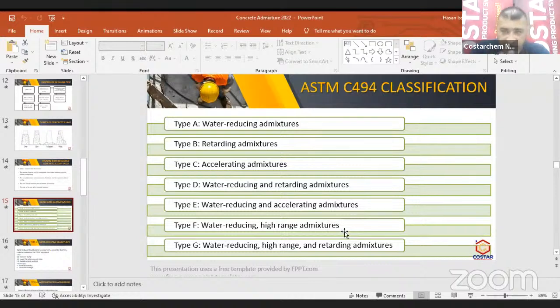It's called ASTM C494. You are all engineers, so I'm sure you know all about it, but I really recommend that you memorize this. This is the Bible of all types of admixture. The Bible. This is the one. In ASTM C494, it talks about SNF admixtures.